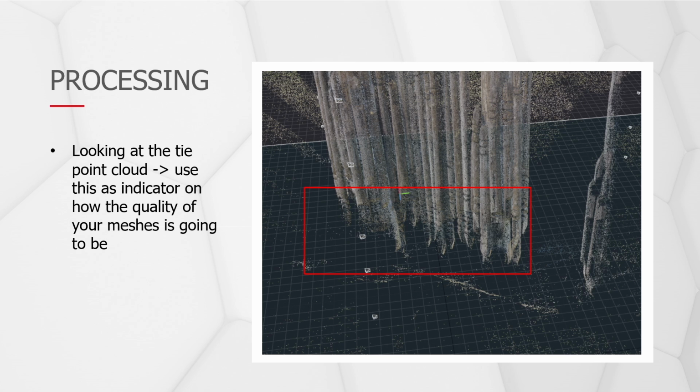some handheld shots. Okay, so let's say that we weren't able to fill these in. How is that going to affect the end result here? Yeah, if you notice that there's not a lot of points in that particular area, what's going to happen in the meshing and the texturing step is it's going to triangulate some of these points that are further out. So you may not have the same fidelity and detail as you would if you did have those points there. And obviously it will ruin the photorealism of these models. Right.